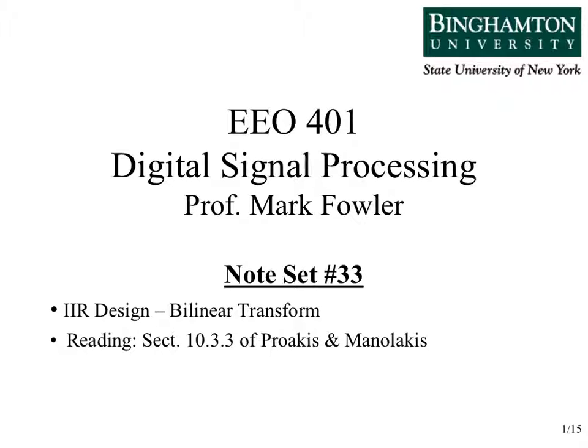So, like I said, here we'll be talking about this thing called the bilinear transform, and technically, transform is a bad name there. It's not like a Fourier transform or a Laplace transform. It's really more like a mapping. It's a mapping from the S-plane to the Z-plane. But nonetheless, bilinear transform is the name that has stuck to it, and this is covered in section 10.3.3 of Proakis and Manolakis, and they give a way of motivating it. I'm going to give a slightly different way, well, a very different way actually, but we end up at the same place.